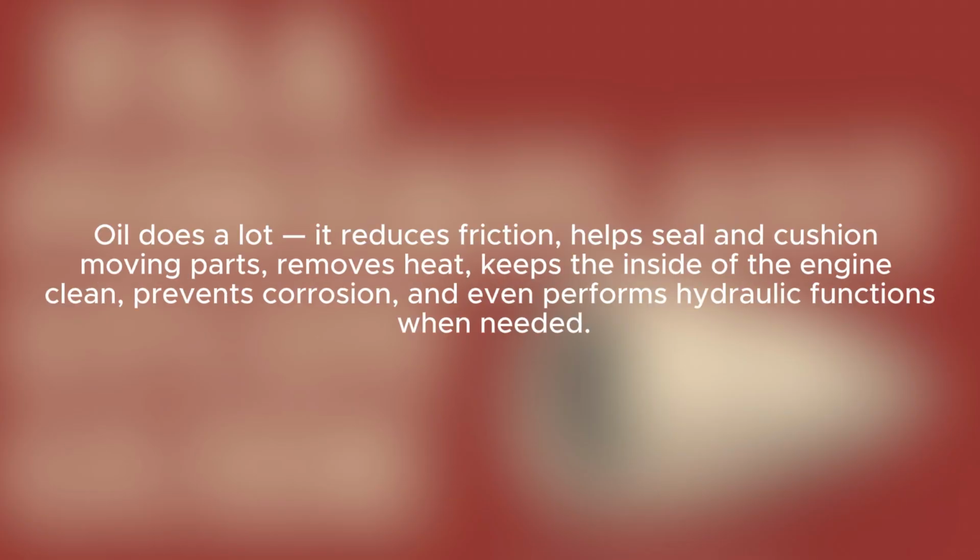What are some of the main jobs oil performs in an engine? Oil does a lot. It reduces friction, helps seal and cushion moving parts, removes heat, keeps the inside of the engine clean, prevents corrosion, and even performs hydraulic functions when needed.